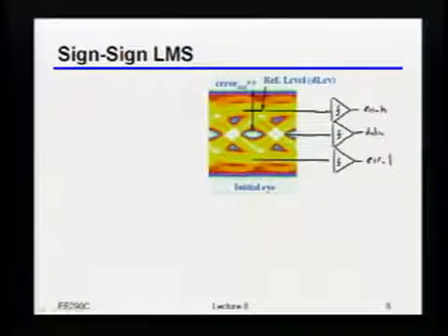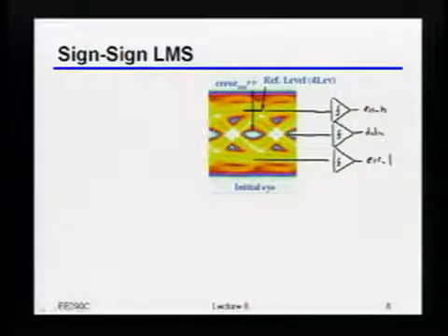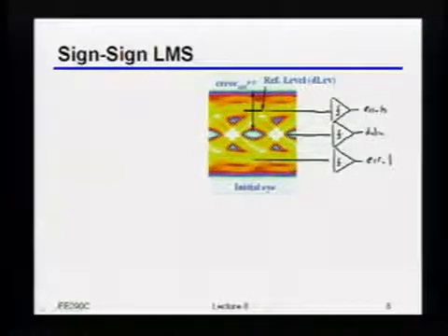There are things that are called sign-magnitude LMS, where one of the things that you deal with is the sign, meaning only 1 bit, and the other one is analog. There's the reverse, which is, I think, sign regressor or something like that, which means the other thing is analog and one of them is the sign. And then finally, sign LMS is the lazy man's version, which of course is what we're going to be doing here, which is just you do 1-bit estimates of everything.